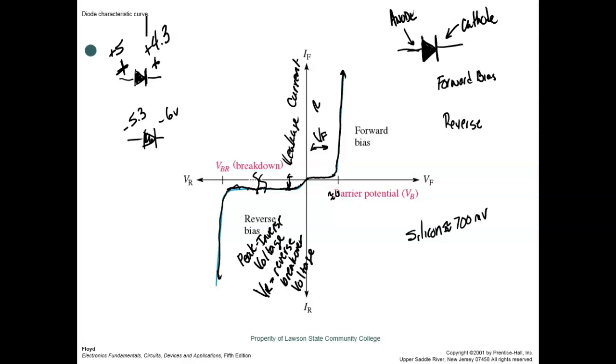So the part number, by the way, most silicon diodes start off with a 1, indicating one junction, and then it comes over here and it's got a designator, and this is pretty standard. So if you ever pick up a part and see a 1N something, then it's a diode, right? If you see a 2N, it's going to be a bipolar transistor, but we'll get to those.